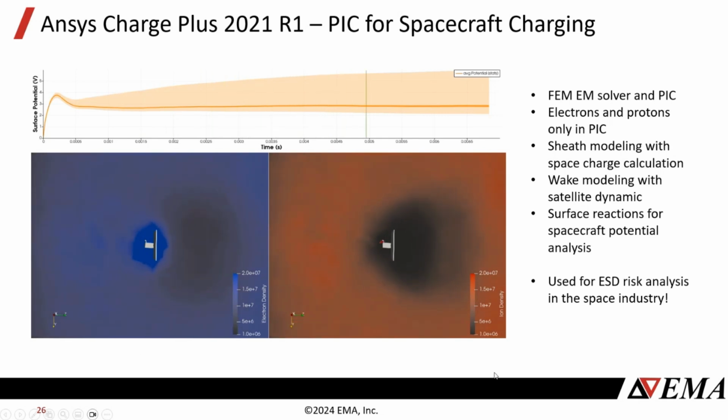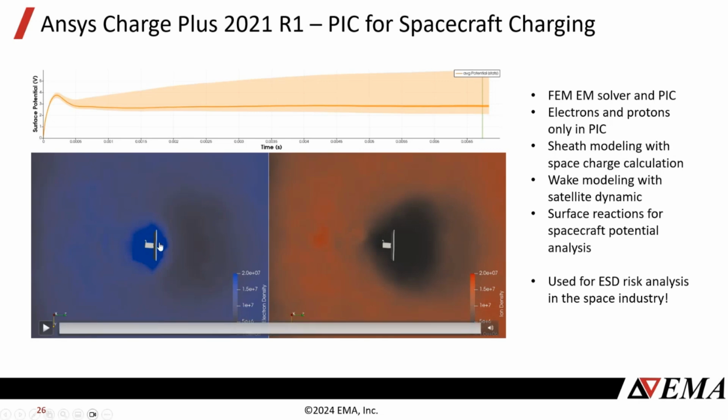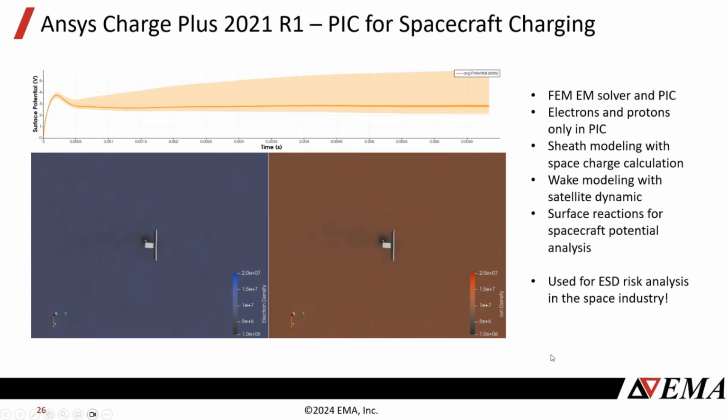So here, the sizes are very large, and because the densities are so low as well, the plasma sheaths are much larger, and you can resolve it with numerical methods and meshes that are not that complicated. But when you start increasing the density, then you have to refine your mesh, and it makes the problem even harder, as we know, for these plasma chambers. The key for this application in the space and defense industry was to understand the risk of electrostatic discharge across surfaces that are charging differently in the system as they interact with the plasma.